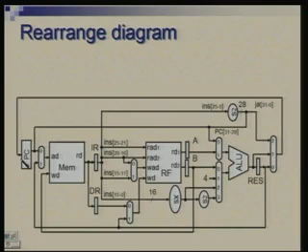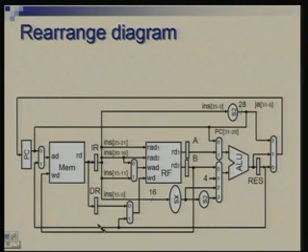Okay. In every cycle we need to determine whether a new value goes into this or does not, because there is no register which is now loading a new value in every cycle. So, this needs to be taken care of, and the number of control signals therefore is quite large. We have these 6 multiplexers, out of which 2 require 2-bit input.